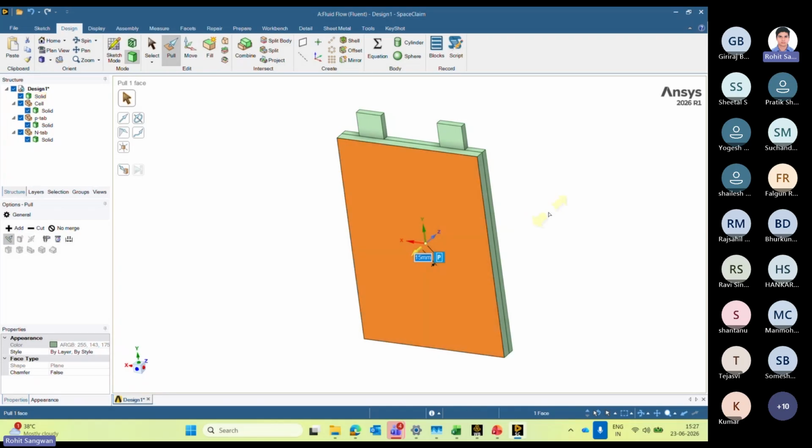Now this is like a part. Somewhere you might have a cross section at the inlet. I can provide thickness, and there is the P parametric option. In future, if I increase the thickness of my cooling channel, since this is a single cell we might not see that much change, because most of it will take away from this direction. The surface area will increase definitely and there will be better cooling. So I can make it parametric, and at different thicknesses we can study how it changes my cooling temperature. With respect to design, you can go with parametric.